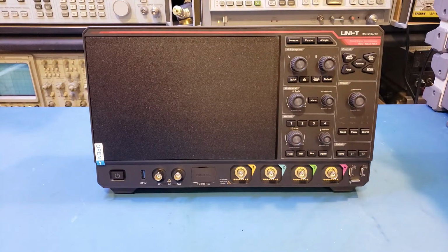Now, I combed through the specs of both the MSO3000X series and MSO5000HD series, and the main hardware difference, besides the bandwidth, is of course that the HD series offers 12 bits vertical resolution versus the 8 bits in the MSO3000X series. The other specifications are actually quite comparable between these two scopes. Now, in theory, I should be comparing the specs between the MSO5000HD series and the 3000HD series, as both are 12-bit scopes. The reason I chose to compare against the MSO3000X series is because, spec-wise, the 3000X series is actually much closer to the 5000HD series.